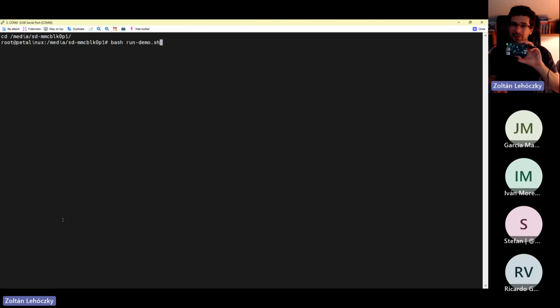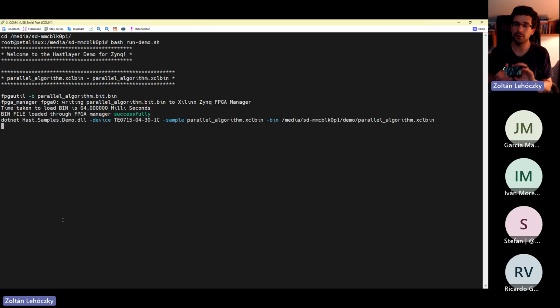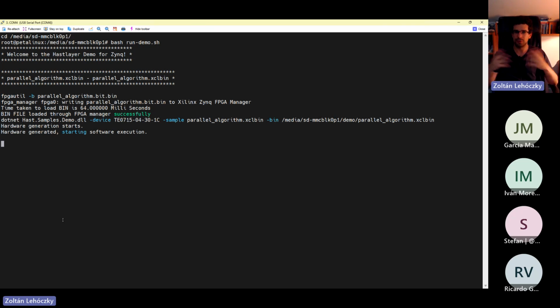So this is what I'm remoting to in this shell. This runs a little Linux. And what I'm running here now is a demo application. This onboard computer that goes on board of satellites has an ARM CPU, so something that you also have in your smartphone. It's a 2-core ARM CPU that's packaged together with an FPGA. It's called the Zynq platform, and it's widely used in space tech applications and also onboard of drones.